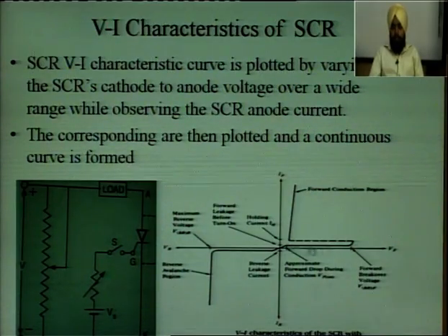So, this is the point where current will start conducting without the gate supply. At the moment the forward breakover voltage point is achieved, the voltage across the thyristor will reduce to a minimum value and the current will shoot up and increase abruptly. So, here you can see the current increases abruptly. This is the forward conduction region, the current which is flowing from anode to cathode.